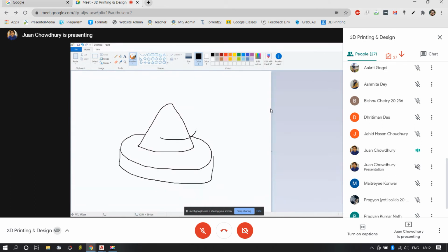The base frame can rotate by theta angle, for example, and then I'll have an arm on top of it, and a second arm, and a simple C-shape gripper, just pick and place. So how many degrees of freedom do I have over here? That's 1. The rotation is possible over here, that's 2. Theta 1, 2, and 3, theta 3.